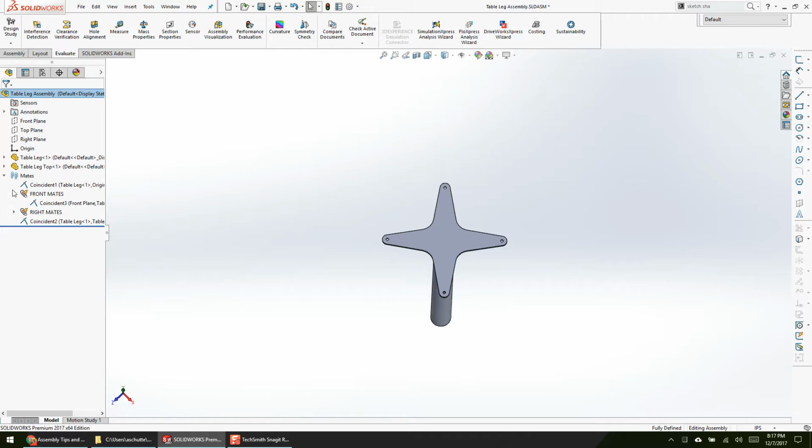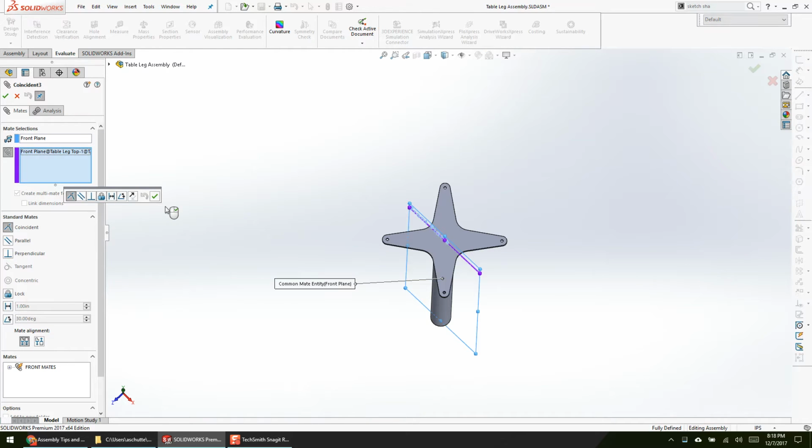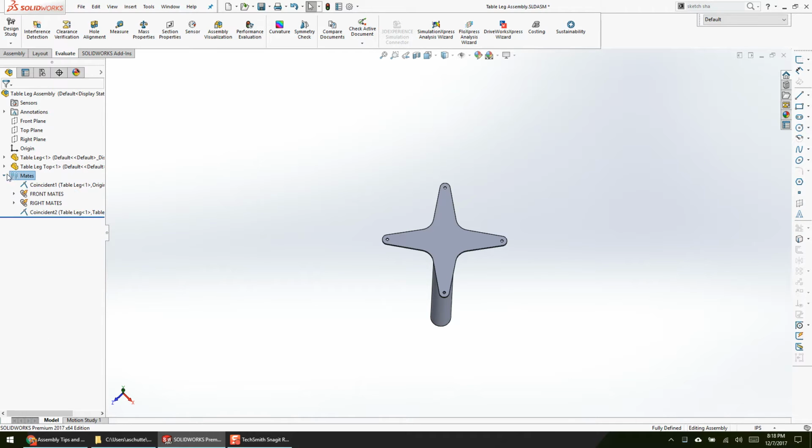So you can add more. I'm going to still add legs. I'm still going to add the plastic beauty ring and the bushings and the cap and a whole bunch of other random stuff, right? So I want to think ahead and say, when I'm constructing my assembly, what else am I going to add? Is it going to be designed properly along center origin with mate alignments or plane alignments? And I can edit my front mate at any time and then add that other constraint, minimizing my mates, maintaining my performance, and minimizing my liability as I continue through my design.